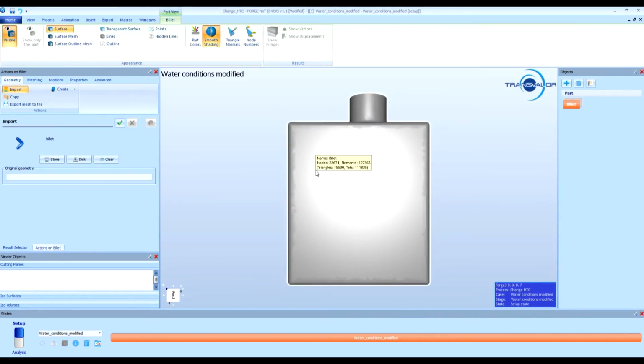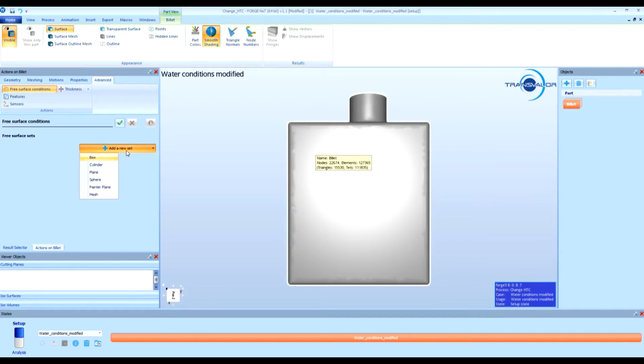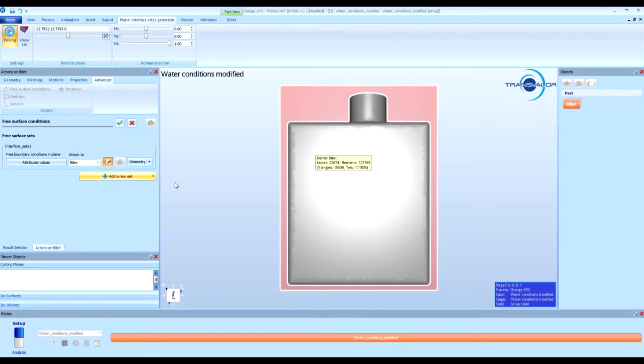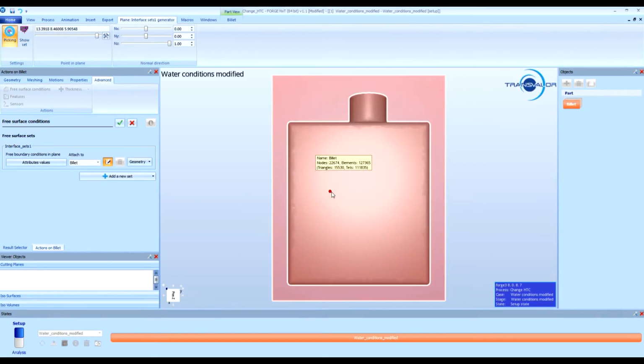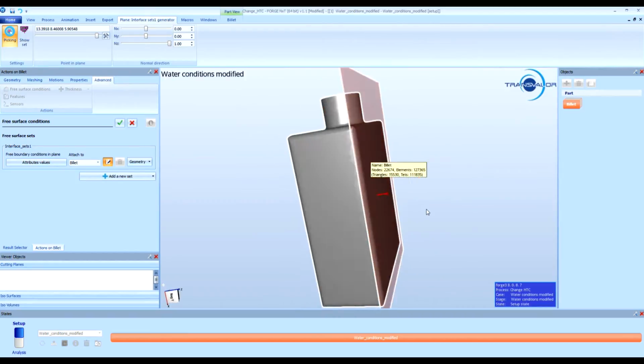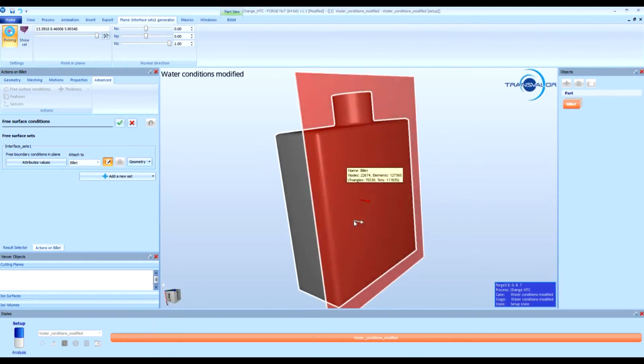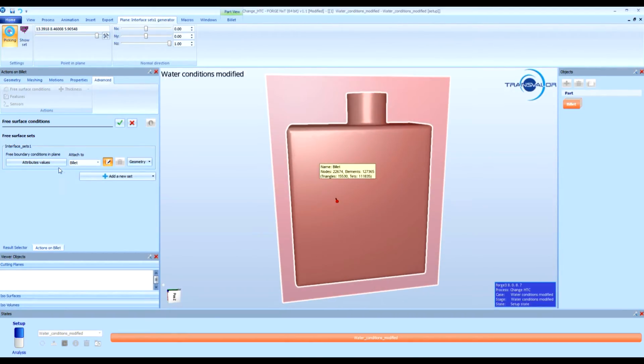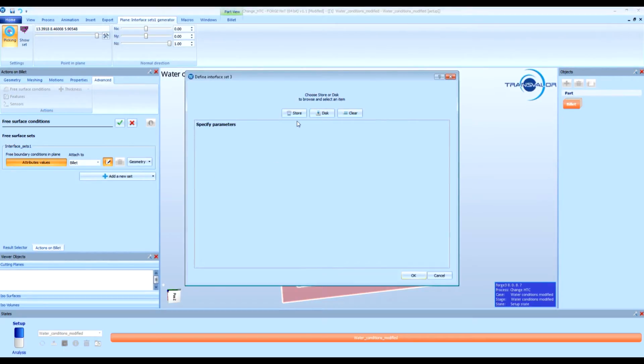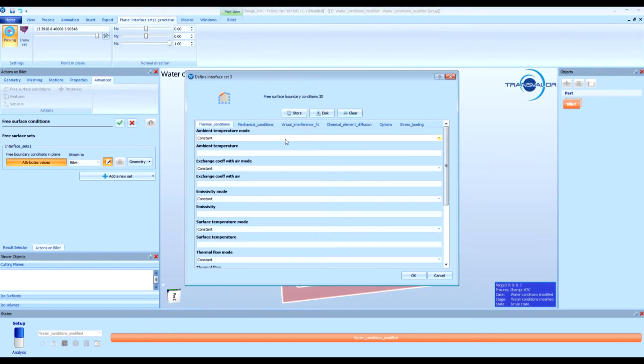We consider a local temperature lower than the homogenized quench tank due to the jet at 70°F. In the heat transfer coefficient field, we double the heat transfer condition normally considered for a homogenized quench tank. The specified surface will cool twice as fast as the rest of the part in this example, and assuming a lower local temperature of the water.